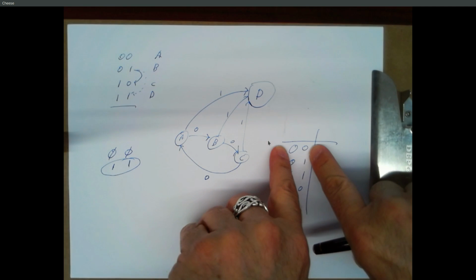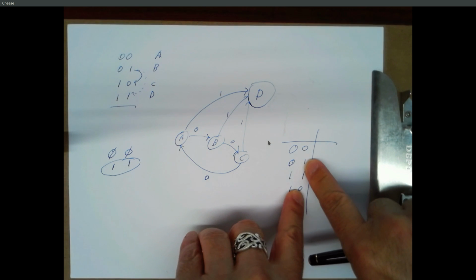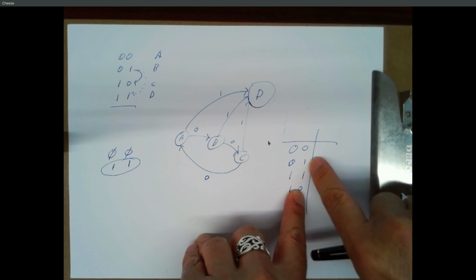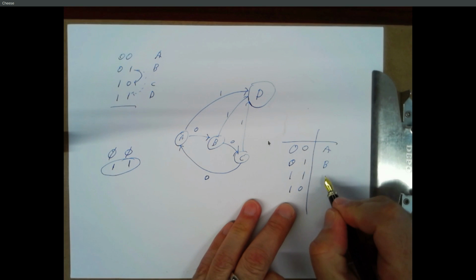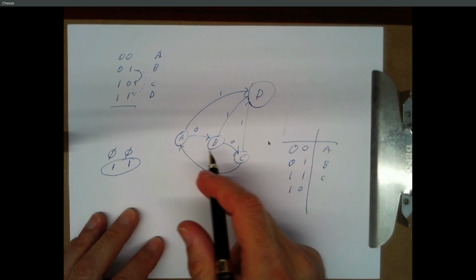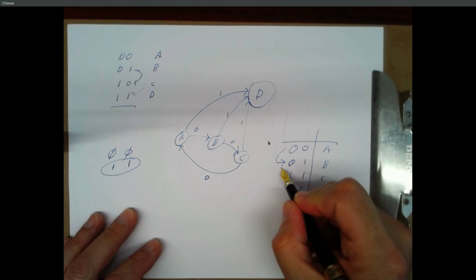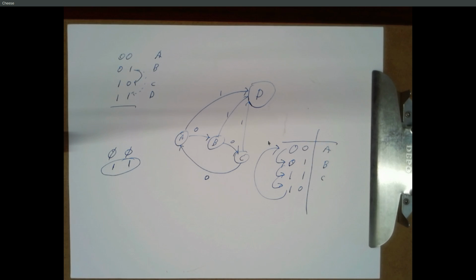But the idea is with a Gray code, when you go from one state to the next, you only have one bit changing at a time. So it doesn't matter how quickly this state changes from a 0 to a 1, this output, you're either going to be in state 0, 1, or whatever that next state is, and I would number these A, B, C. But my analogy doesn't work because going from C to an A, you've got another potential glitch. But assuming that you're using the full Gray code sequence, so if I had 4 states here, when you go from one to the next, to the next, to the next, and back to the first, you can't have a glitch, right, because only one bit changes. So it eliminates a potential race condition that can give you an illegal value.